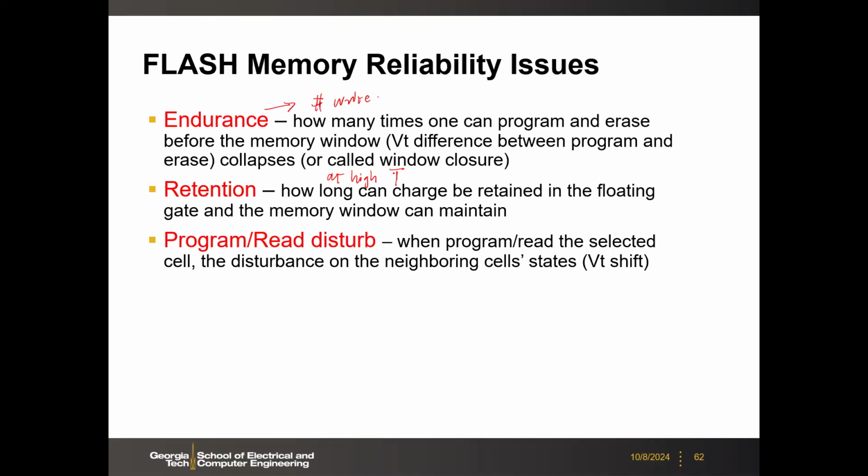So also the NAND flash has this program and read disturb issue. We already briefly talked about that earlier when we talked about the program erase schemes. So basically, when you program or read the selected cell, the neighboring cells' VTH might shift. So that is the disturb.